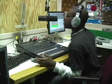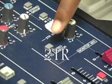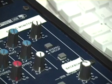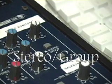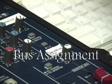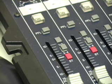When you're doing your broadcast, make sure these buttons on the board are in the following positions. 2-track channel labeled 2TR set to stereo, up. Stereo/group set to stereo, up. Bus assignment 1-2, up. All other fader channels, ST and 1-2, down.